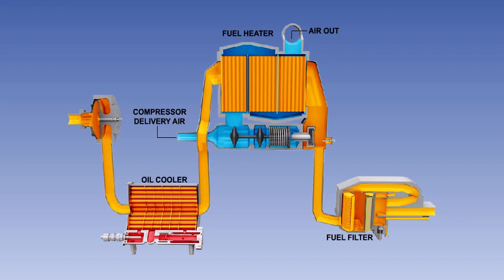Some systems utilize a fuel-cooled oil cooler as well as or instead of a fuel heater. The fuel-cooled oil cooler uses the hot engine oil to warm the fuel and in doing so produces the added benefit of cooling the oil.